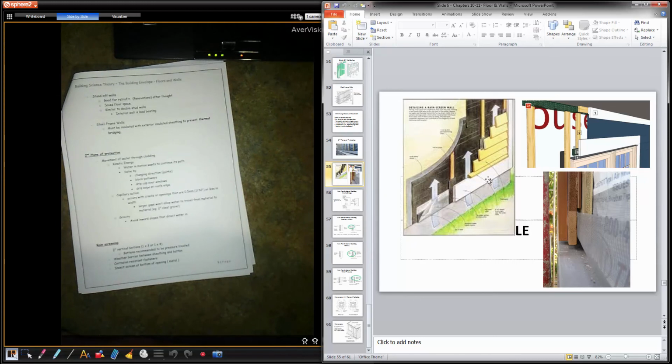So that's your first plane of protection, your siding. Second plane of protection is the tar paper. And then we have a buffer in between, so strapping with gaps to allow water to get out. You don't want water trapped tight between the tar paper and siding, because then it works its way through the staples. It's under pressure, so it's almost forced to stay where it is. It can't fall. If you create a gap between the two products, it allows the water to come out. It also allows air to flow up into it to dry it out.